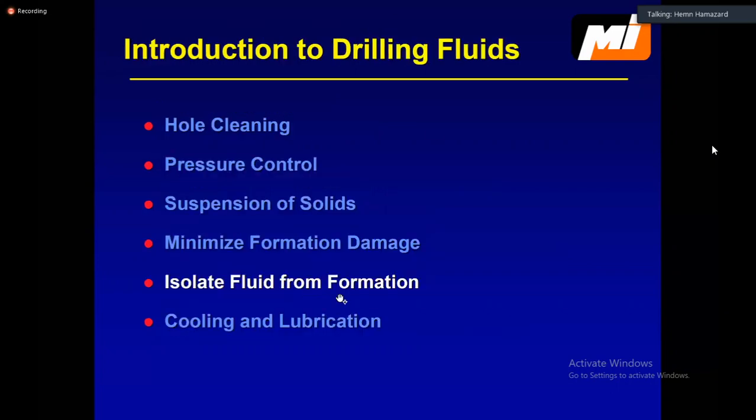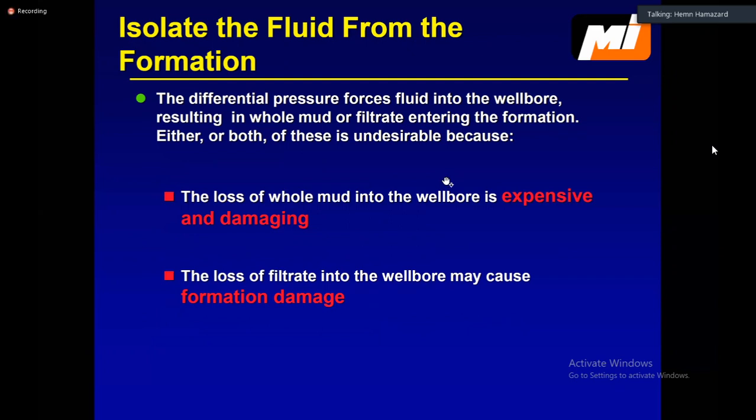And then isolate fluid from the formation. Like I said, you have a window. If you have mud above the window, if it's below the window, you end up with well control. You're going to have a kick. But if it's above the window, above the fracture gradient of the formation, then besides breaking the formation, you will also have a problem with what they call differential sticking. Differential sticking is one of the sticking mechanisms.